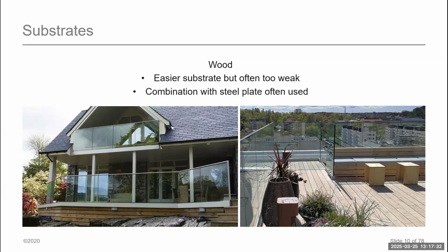So when we get into a situation where we're fastening into wood, a typical GRK screw that's about 4 inches, fully embedded, will have a withdrawal or moment resistance of about 1,000. So then we need to do one of two things. We need to either start moving to lag bolts at a 1/2 inch diameter, and we need to start increasing the embed depth down to about 8 inches.